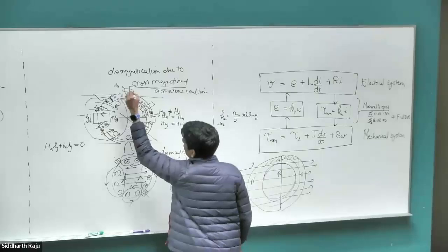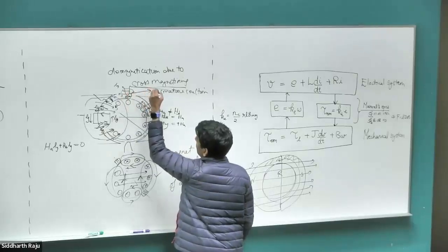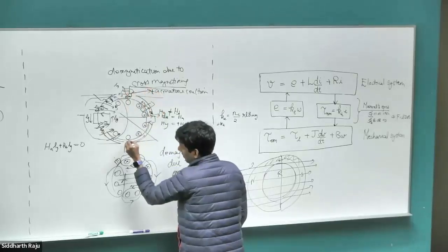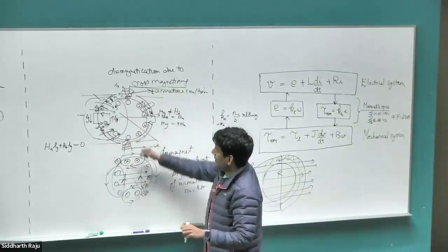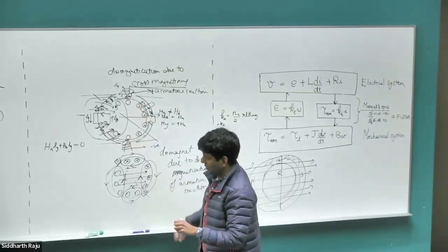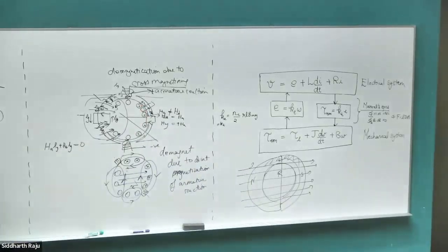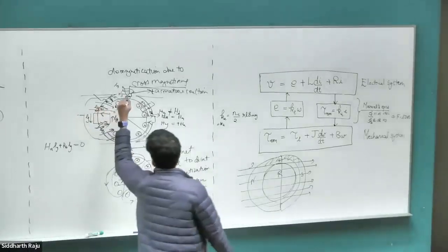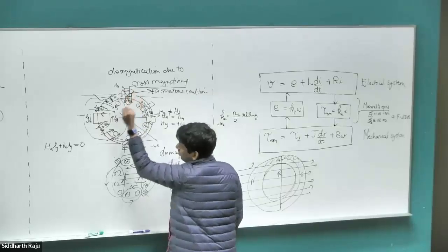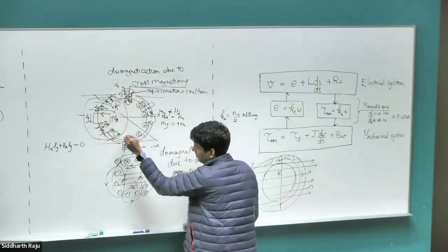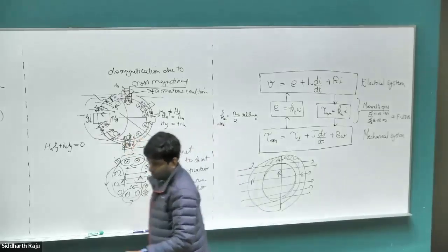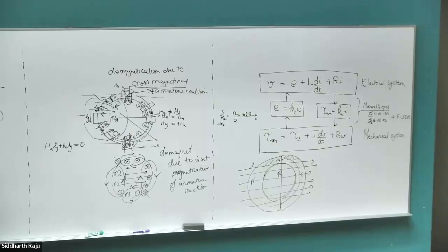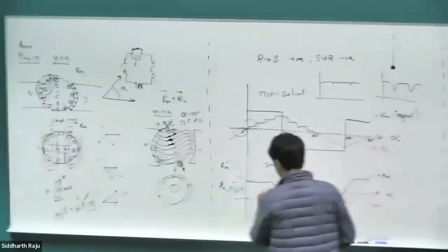So this wire comes out and it's wound on this, and then this wire comes out as some positive terminal, let's say, and then the brush would wind on this and then come out as the negative terminal. So whatever current flows in the armature is flowing in this winding as well. So we can operate this in such a way that the magnetic field created due to this is opposite the magnetic field created due to the armature reaction. Oops, sorry, the other way. Right, so what in effect we are doing is reducing the height of this armature reaction.